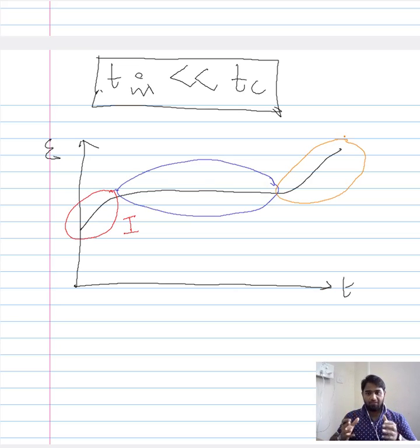If in some material the instantaneous creep is, as its name suggests, very instantaneous, or rather the time taken for the instantaneous creep is negligible compared to the overall creep period, then the overall creep curve will begin with the instantaneous creep, or rather transient creep, and then stage 1 should be categorized exclusively by the decelerating creep, or the transient creep.